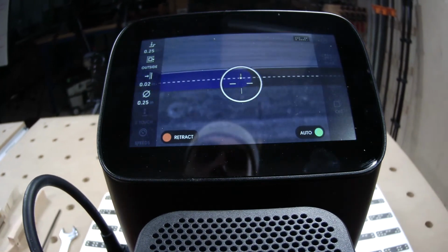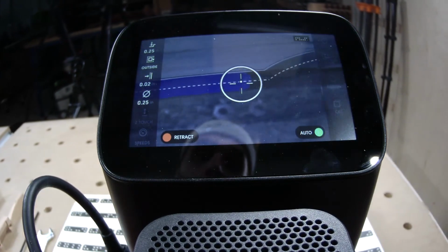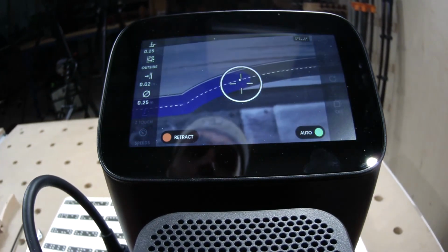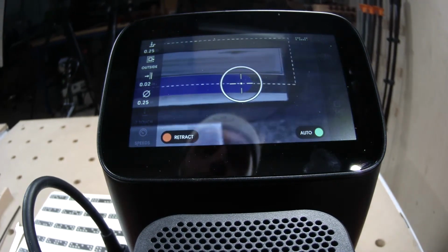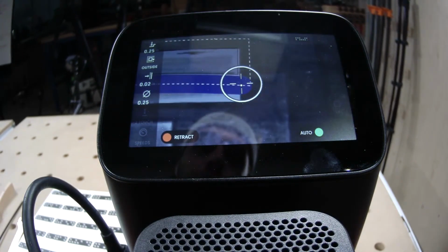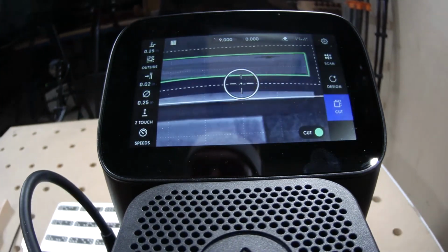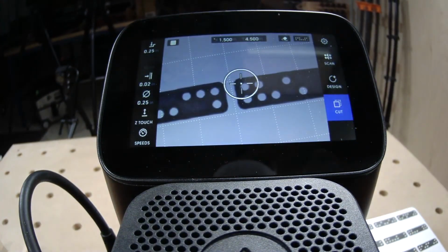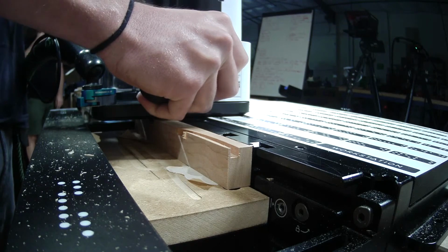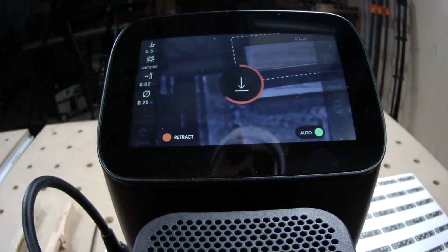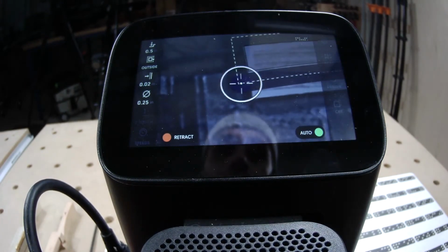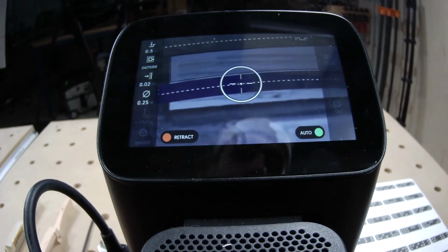Yeah, I have to walk out the door maybe. Sean's going to be cutting down, and he's going to be increasing his offset further away by just a fraction. And what that's going to enable him to do is to cut down to like 3/4. So that's using the full cutting flute. And then if he moves away ever so slightly from that, he can continue cutting a little deeper. And that'll hopefully get him to his full depth he intends to cut there.